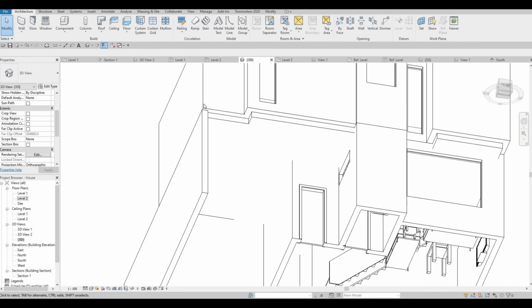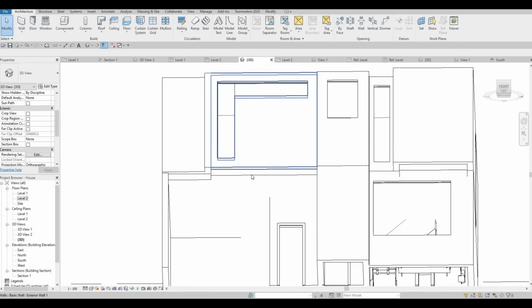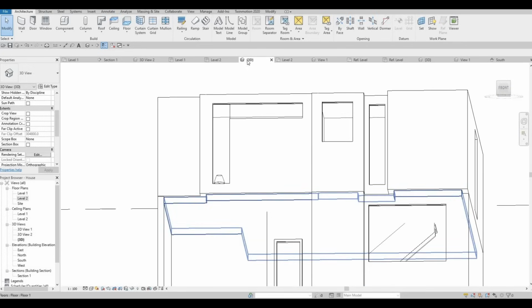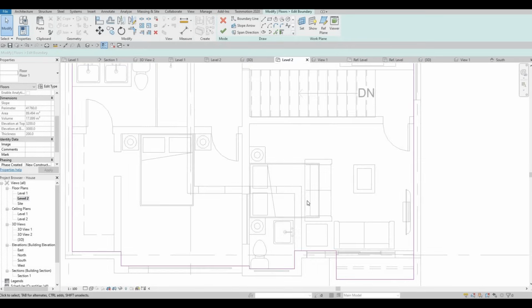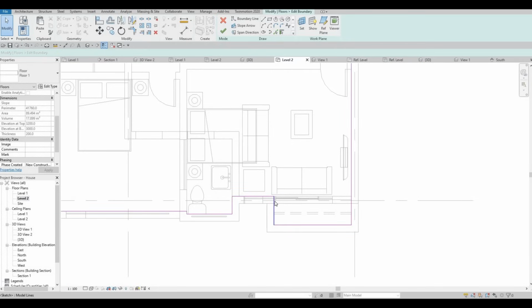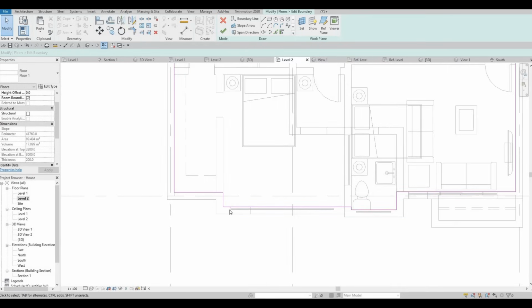I think it's better for me to go all the way here. The reason for that is this will be covered anyway, and then this one I'm gonna pull this back. So here it is. Use TR, trim and extend, and then delete the extra. So for here, I want to TR, remove this, and actually I could extend it here, EL. I think there's gonna be an error here, or no.